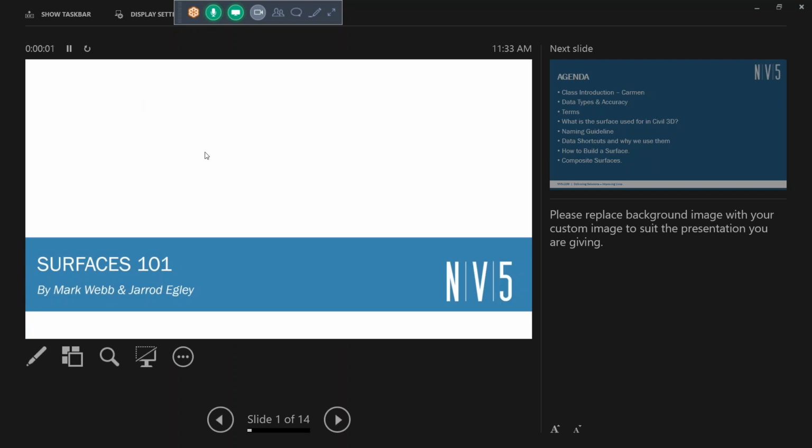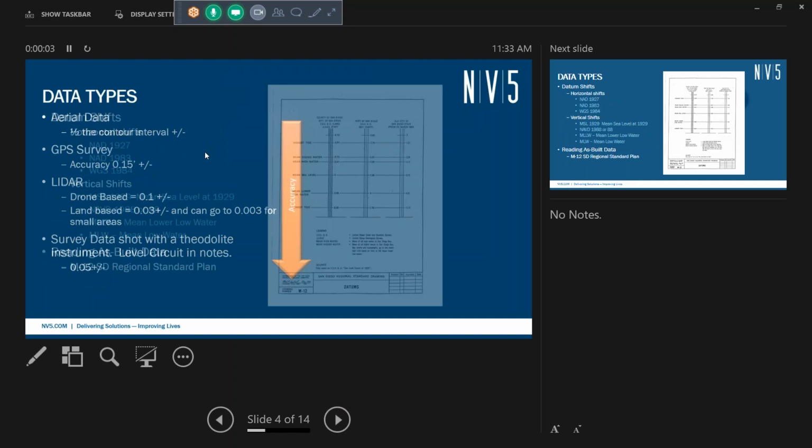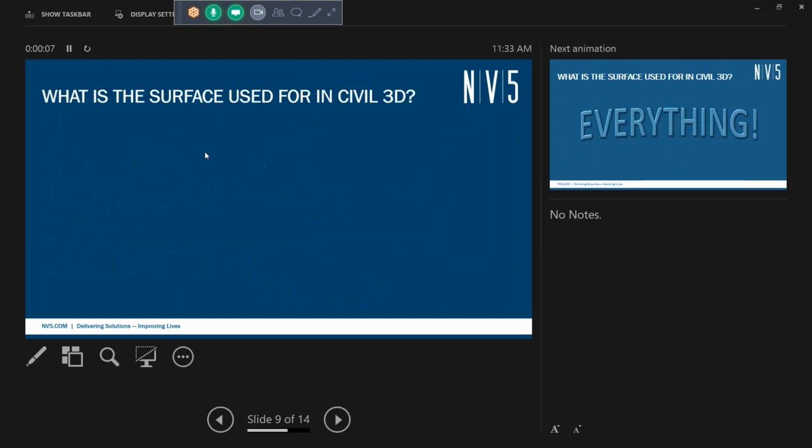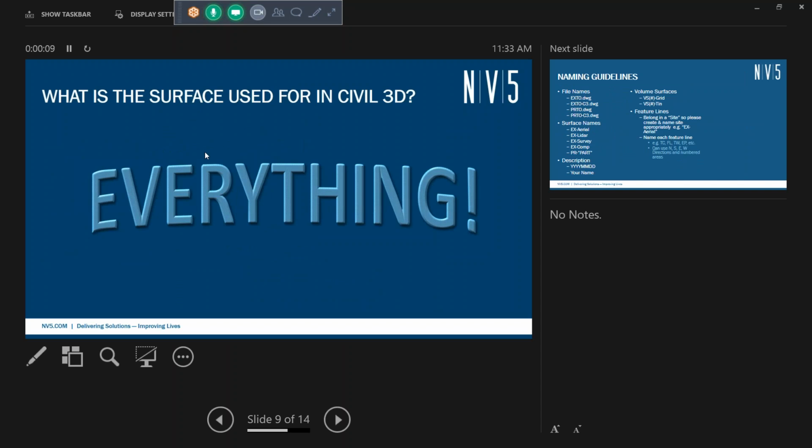If it's plus or minus a tenth, because that's all you're using, then remember, if you need to set a trench down at 3 feet, it is plus or minus a tenth. Our survey crews take care of that out in the field, but not always.